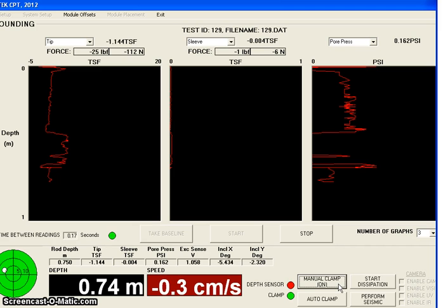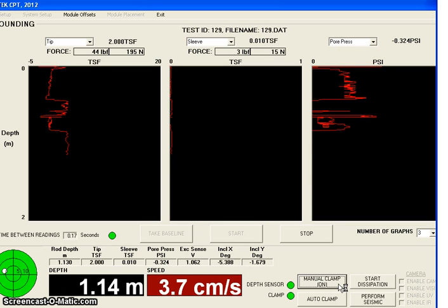You can see the data goes merrily on. Since I'm in a manual situation, should you forget and go back up, you see that data's going back up. So it's keeping track of where it is because it says I'm clamped. So if I'm moving, I must be gathering data. If you had switches in position to know when you should be gathering data, or pressure switches, then you would auto clamp as you were in and out of position rather than having to manually clamp. People using on drill rigs and whatnot just go with the manual clamp usually.